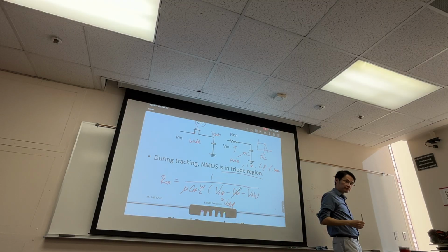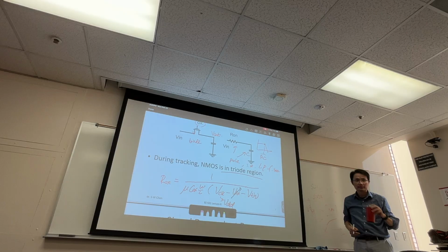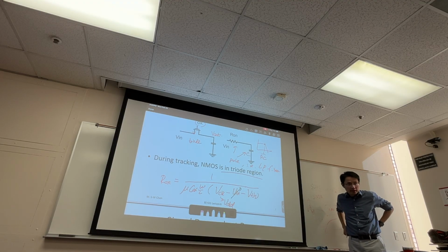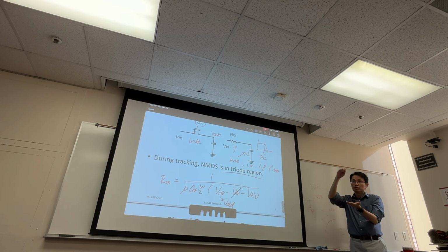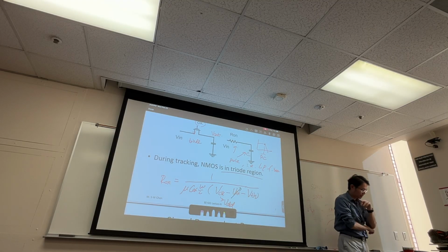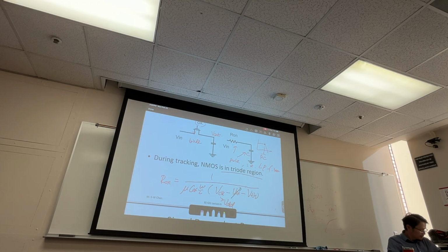Can you put a buffer with VDD and VSS for the whole range? Yeah, so you will have some kind of drivers or buffers up front. But no matter how you bias that buffer, it still comes down to what your input swing is, right? Because if the input swing to that driver is small, then the output coming out of it has to be small. So it's all end-to-end system design, and you've got to work with the previous block designers to figure it out.